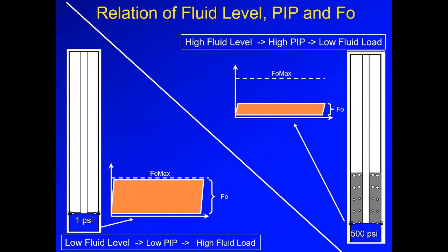And the dynamometer card height that we have in the well corresponds to some pump submergence. So the lower the pump submergence, the taller the dyno card shape is. And the opposite, the higher the pump submergence, the higher the fluid level in the well, then the thinner the card becomes, so it gets flatter and flatter, smaller and smaller as the fluid level goes up. And why does that happen? Well, it all has to do with pressure. How much help is the well providing to the pump?